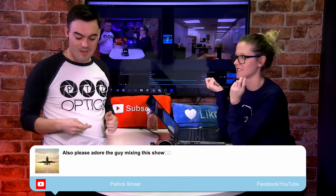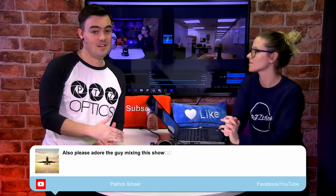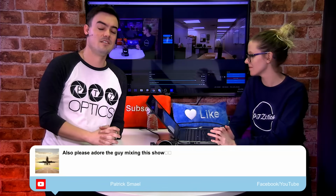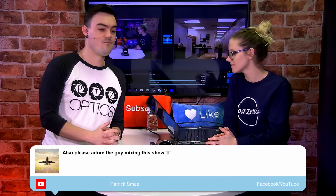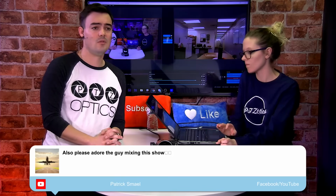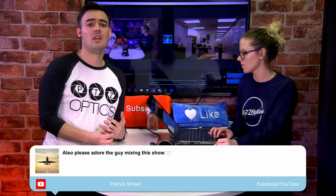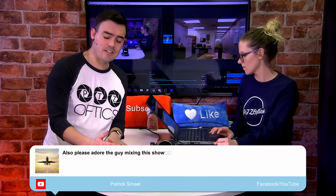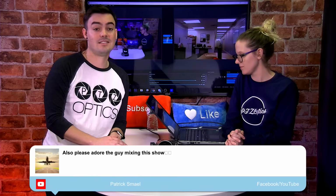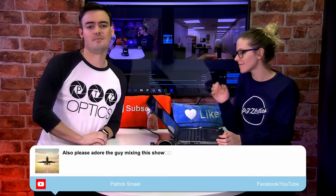The Roland is a really nice switcher, so it's probably receiving the video. It probably has good connectors in there. Our cameras are sending a very clean feed, is what we call it. But if you're going anything over 50 feet, you can go with the NewTek cable, which is apparently 100, or think about just doing a high quality Lumens, Crestron, or Extron HDMI over Cat extender, which boosts the signal on both sides, and then you can just run Ethernet in between.